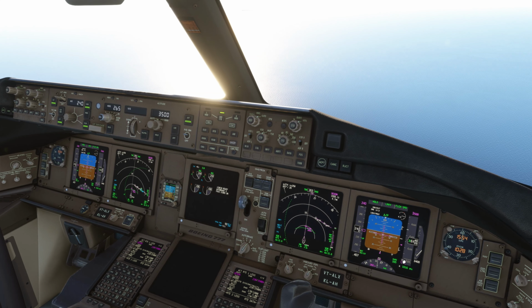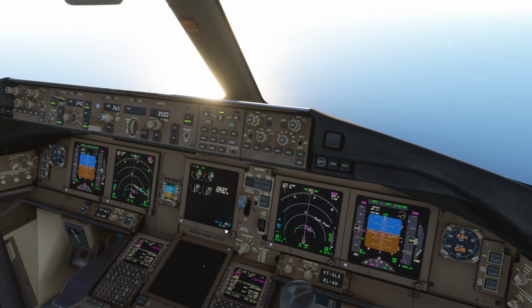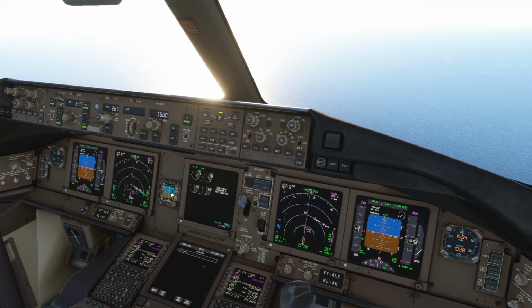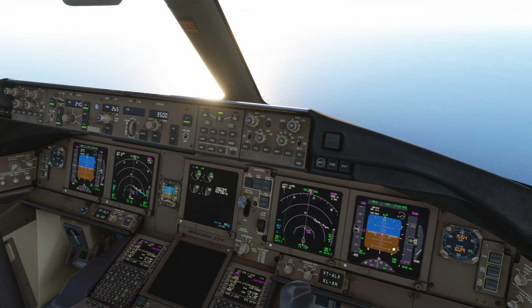Cabin is ready and approach checklist. Altimeter is 1016, descending passing 6,000, cross check both sides. Approach checklist complete, and I'll reduce my speed.